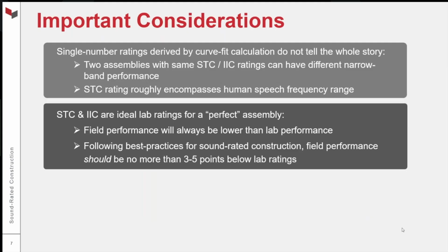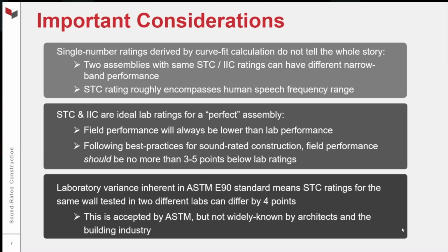But if you follow best practices for sound-rated construction, which we'll touch on toward the end of this presentation, your field performance should be no more than 3 to 5 points lower than the laboratory ratings. I say should because field conditions can vary quite a bit. We're not going to go into that level of detail today, but we will touch on some best practices for sound-rated construction. And finally, and this is very important, I'm going to touch on this a few times today: there is variation in these laboratory tests.